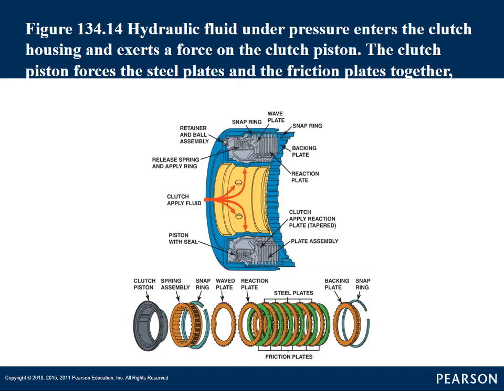They're set at the factory. But there are some cases where you can change this. If you want to beef up the strength of a transmission, you can put more clutches in it. A good example of this is the GM 700R4, you call it the 4L60 or the 4L60E.